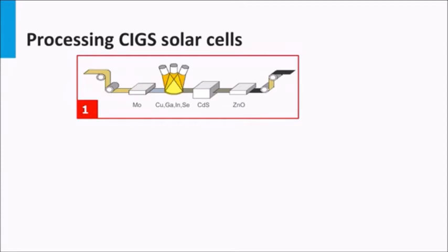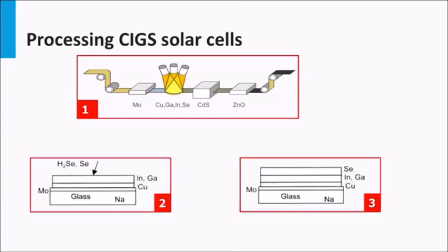The deposited films on the cold substrate are thermally annealed in presence of a selenide vapor to form the final CIGS structure. Another option is to deposit a selenium-rich layer on top of the initial deposited alloy, and this is annealed. Because of the variety and complexity of the reactions taking place during such selenization process, the properties of CIGS are difficult to control.